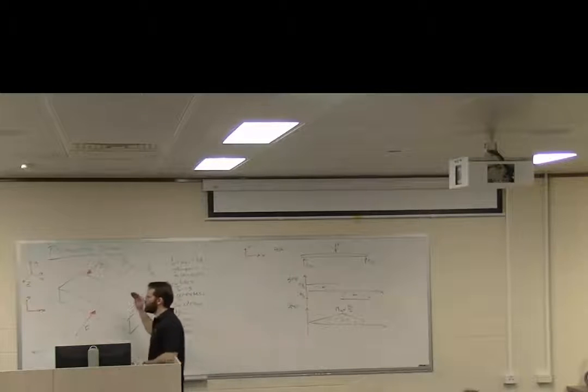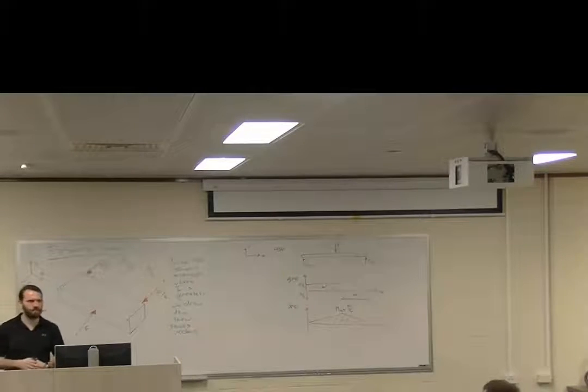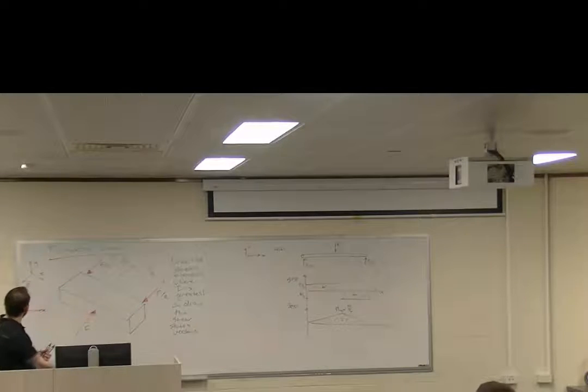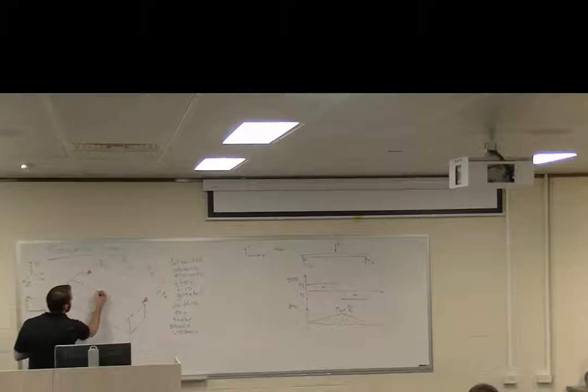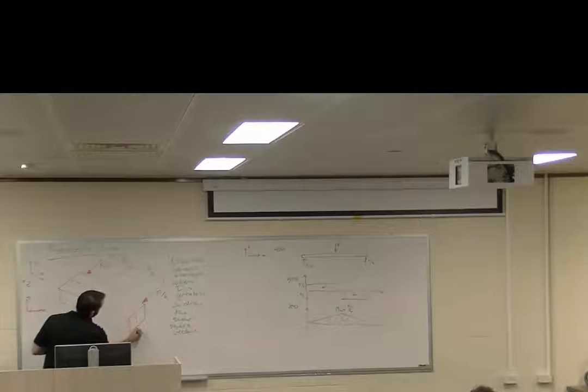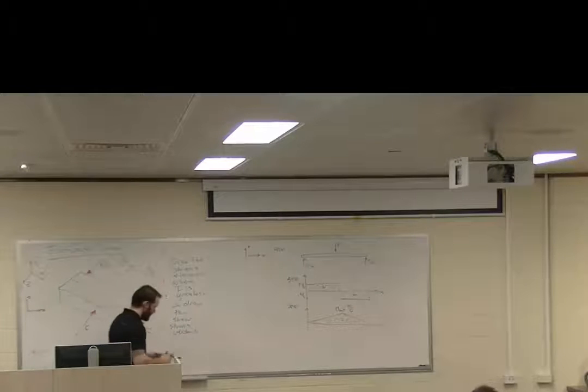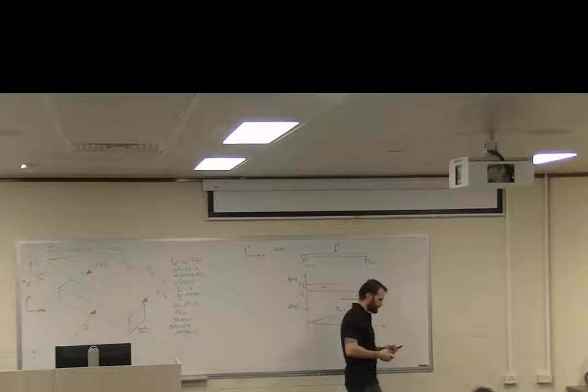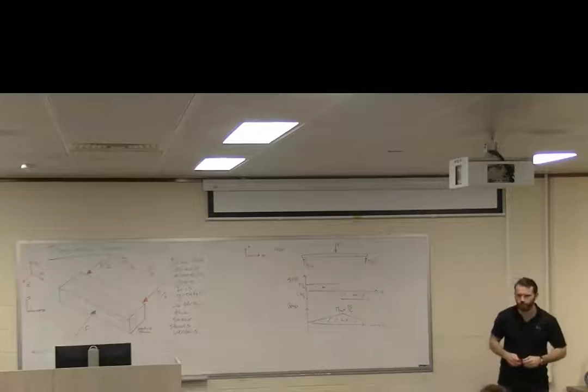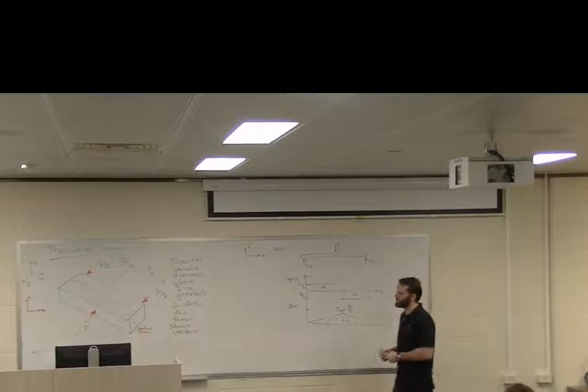Now, where's our neutral plane in this particular image? Yep, so the YX plane in the center, exactly. So if I was to draw that, I'll call that plane. Something along the lines of that. You can even give it some of those ones. All right, so we know that our shear stress is going to be maximum at that center plane. Where is our shear stress going to be 0?